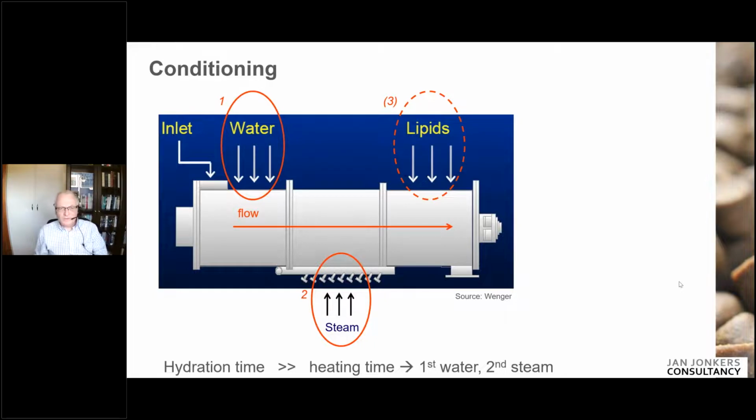Then in addition, it's quite good to add the water at the top of the conditioner and steam at the bottom. Water wants to go down, steam wants to go up. So then you get a good interaction of all the injections with the particles.